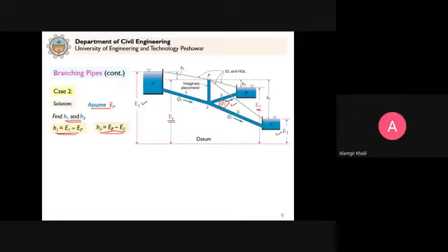So using those expressions, we apply the energy equation between the points. When EP is known, clear, then H1 you can calculate. Clear? So H1 will be equal to E1 minus EP. You see here. And H3, this is H3. This will be equal to EP minus E3.